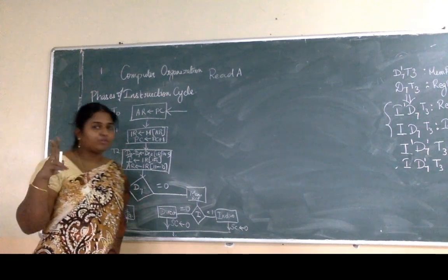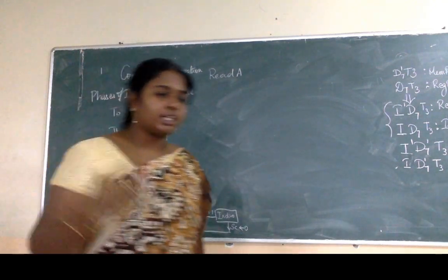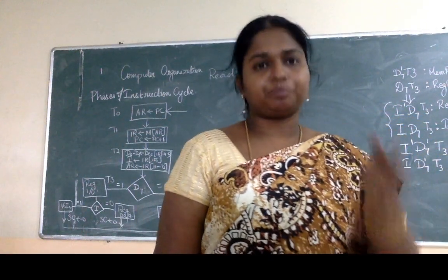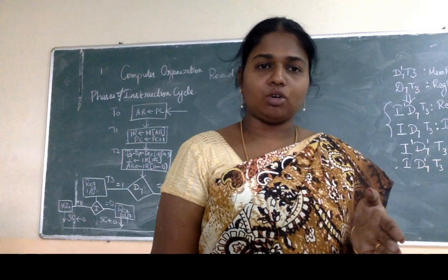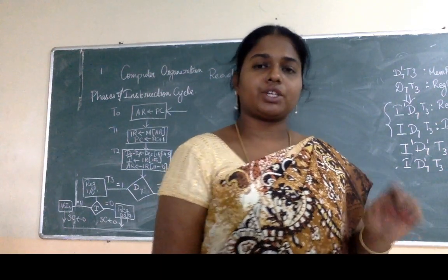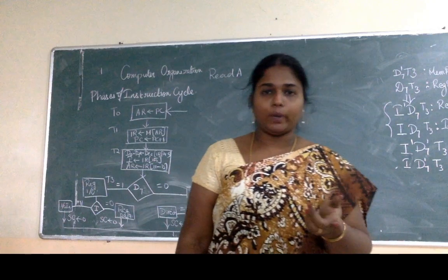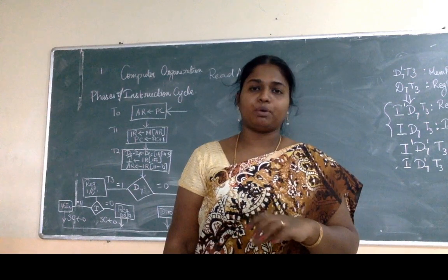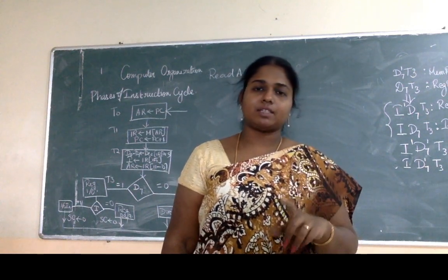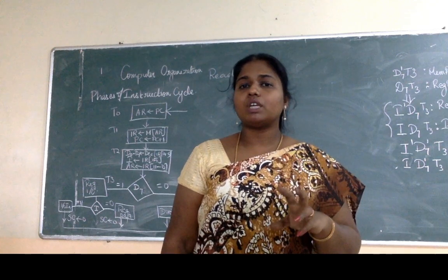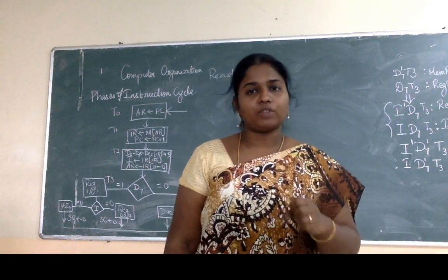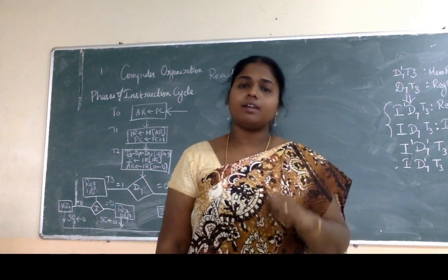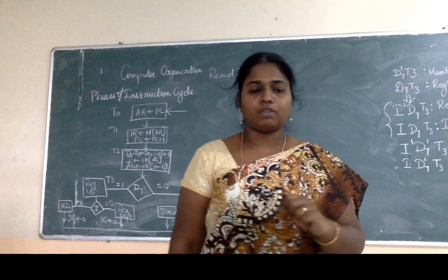The circuit has two different decoders. The first is a 3x8 decoder which takes its input from the instruction register bits 14 to 12, and the second decoder uses the clock input and the sequence counter as input, and generates 16 timing signals T0 to T15. These two decoders form the base of the control unit, and they generate control signals D0 to D7 and timing signals T0 to T15.